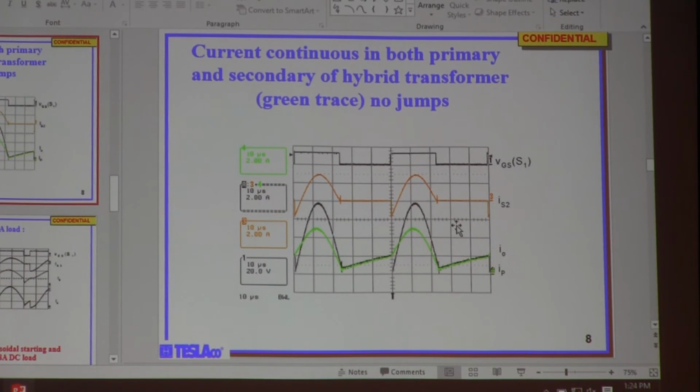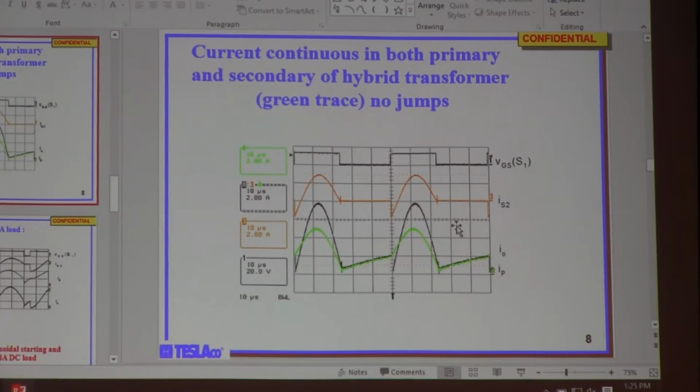And you can make 400 volts to 48 volts to 1. I have an isolated version where I can put an isolation transformer which brings it from 400 volts to 48 volts, and then another tapped hybrid transformer steps it down to 1. So I have no problem making it 400 volts to 1 volt. So why should I even have a 400 volt bus and a 48 volt bus, when I can have a 400 volt bus with low current and no leakage and so on?